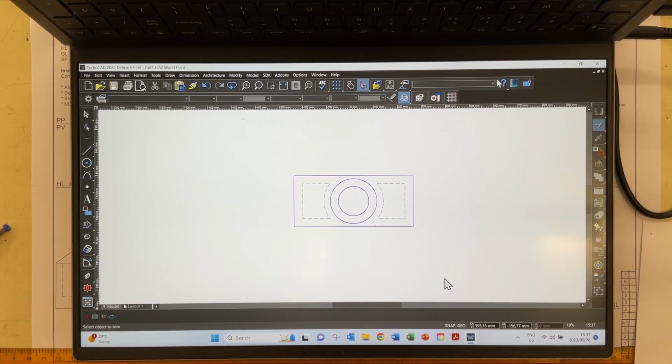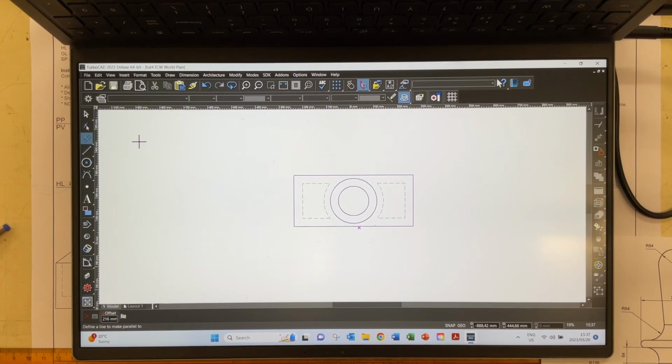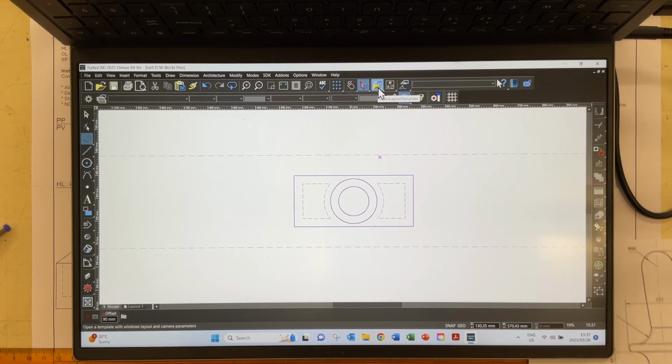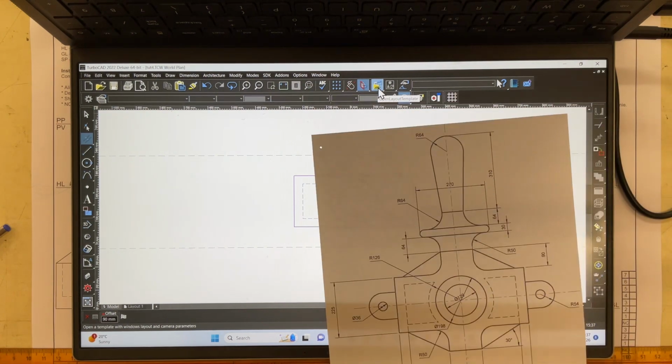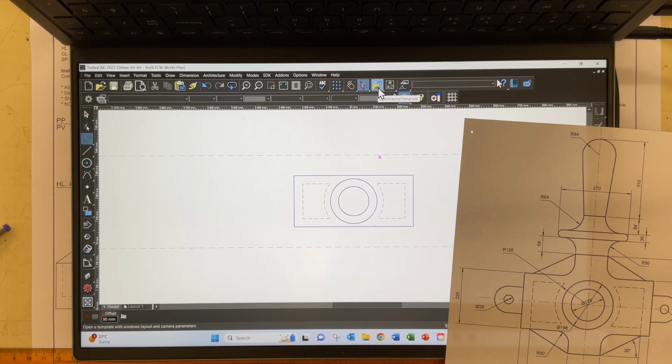My next thing is to come down over here and get these parts in here. It says that I need to go 90 millimeters up, to that line. So obviously, it's mirrored around that axis. So let's go in here, do a tab, this is parallel lines, tab, highlight the little block, press 90, enter, come in over here, click that over there, click that going up there. It says that I need 126 millimeter gap over there, so let's do that. Obviously working off the center lines.